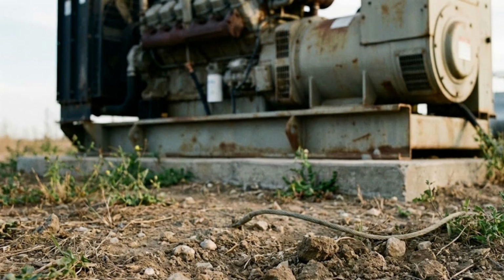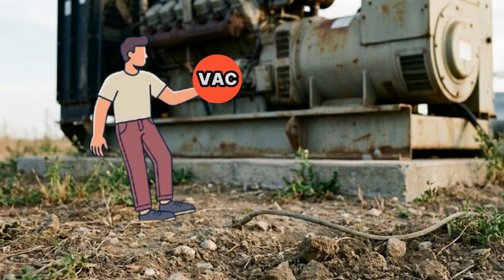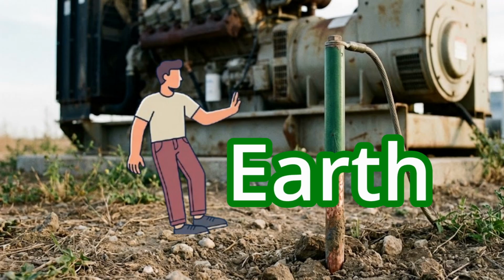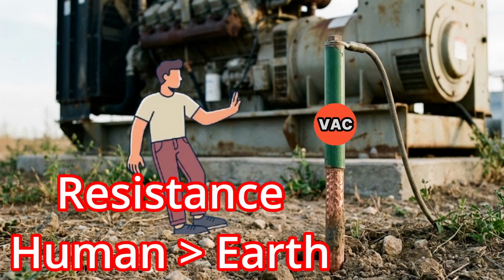What does that mean? Here is a large motor. Let's assume there is a short circuit inside. If a person touches it, current will flow through their body. However, let's assume the motor has an additional ground connection. If we touch the motor, the current will not flow through the human body because the resistance of the ground wire is much lower than the resistance of the human body.